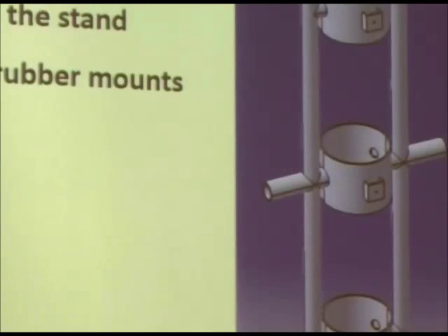So to start, we started out with the handle where we were able to slide the reactor, which is the glass tube, in between the 3 rings here, where we would then clamp down with some rubber feet to center the ring between the supports so it doesn't touch, and then allow for the reactor to sit comfortably inside there.